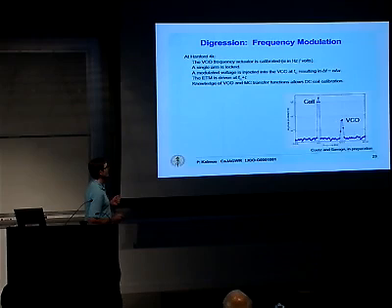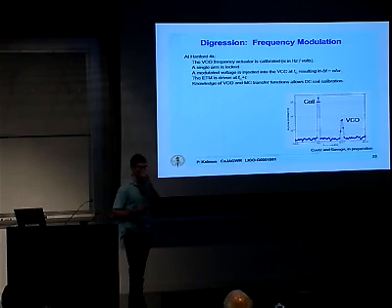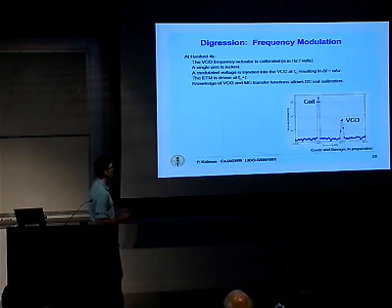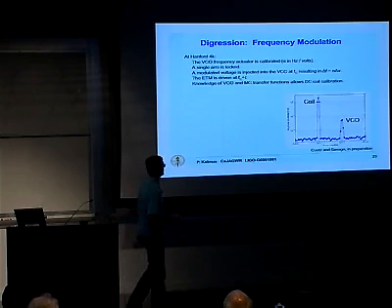So then you can look at that photodetector and put in a peak with that frequency modulation at a particular frequency, and you can put a nearby peak in with the coil drivers on your test mass. If you know the calibration, if you know for a given voltage driving this VCO how much that frequency is changing, then you know the coil drive in terms of meters. You can use that to go to meters there. So again, it's another technique that's relatively simple in principle.